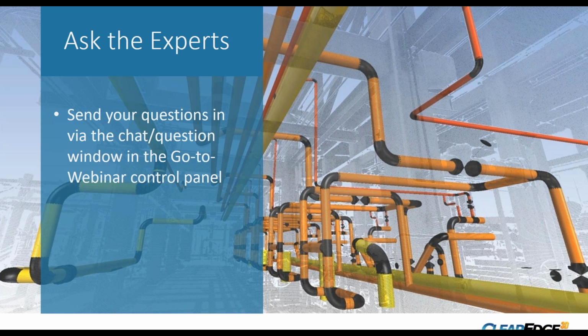So if you have control on level 3 to tie into, you don't need to have a lower tolerance for level 3 than you do on level 1, because that control is going to move with the building as it blows around in the breeze and expands and contracts and all the other physics things that those of us in the reality capture industry have to put up with.